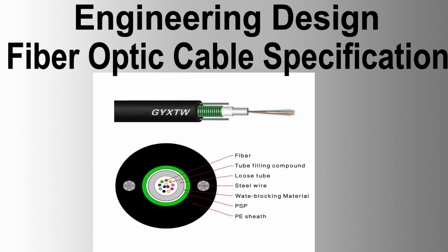HDPE conduit installation test, general. After refilling trenches, the contractor shall perform section-wise pressure and calibration tests for sections of at least 1,000 meters in length. Any damages or deformations hindering the blowing of the fiber optic cable shall be repaired by the contractor, and the tests repeated for the repaired section.